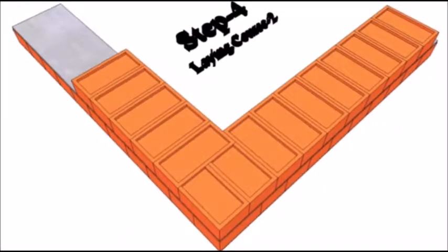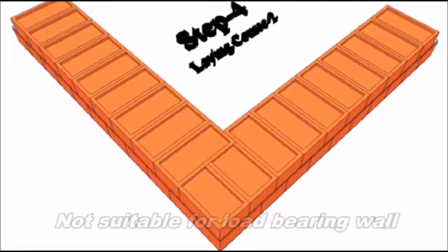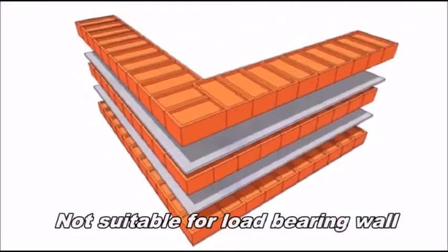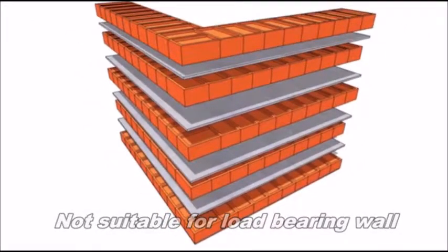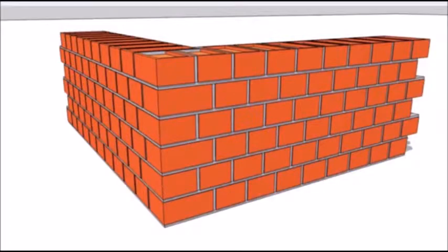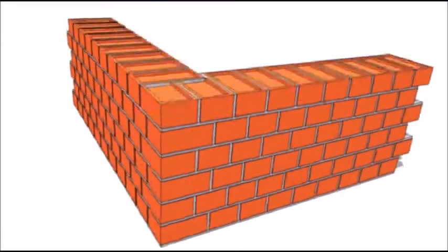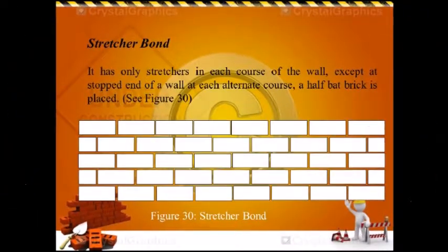Since header bonds lack strength and pressure transmission along the length of the wall, it is not preferable to use this kind of bond for load-bearing walls. I hope students I have made it clear about the header bond with the help of this video.